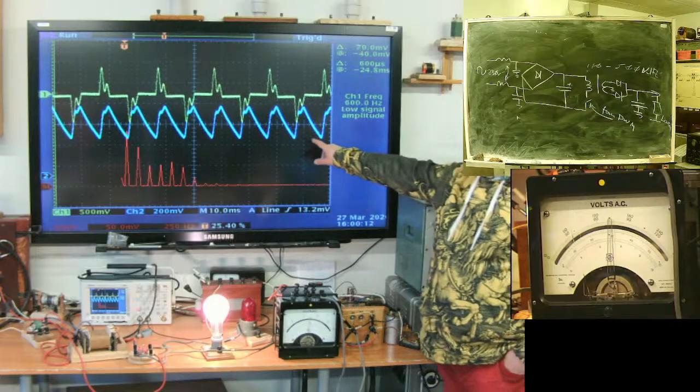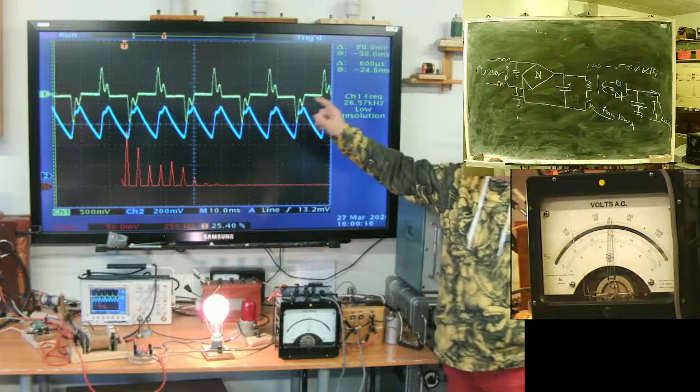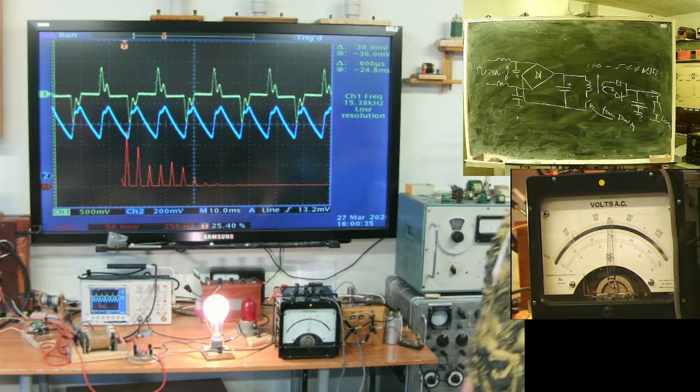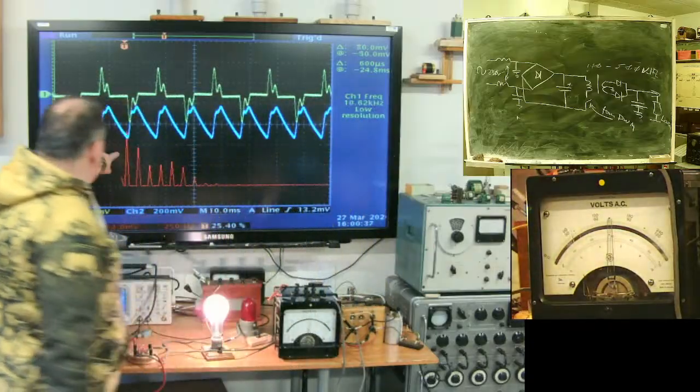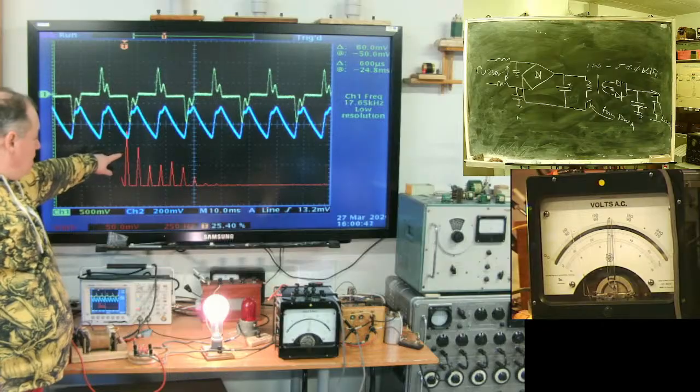Low voltage, this is current. Under the filter, what happens? The filter capacitor discharges. The first diode opens, the capacitor charges, then it discharges, and we see the second opening of the diode, a second pulse of current. Third harmonic, approximately 3/4 of the base.